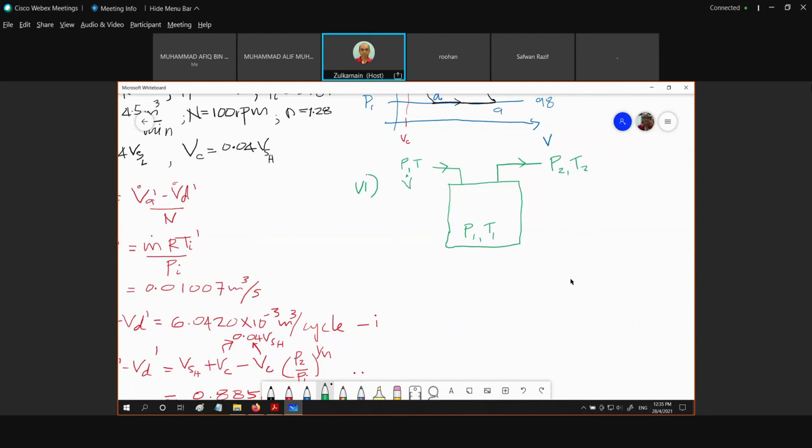How about the m dot? Is the m dot the same for the two stages and the single stage? Yes, they are the same, because we need to get the same delivery, or the FAD, the V dot. So what is the IP? For the single stage, IP is equal to N over N minus 1 times m dot R times T2 minus T1.